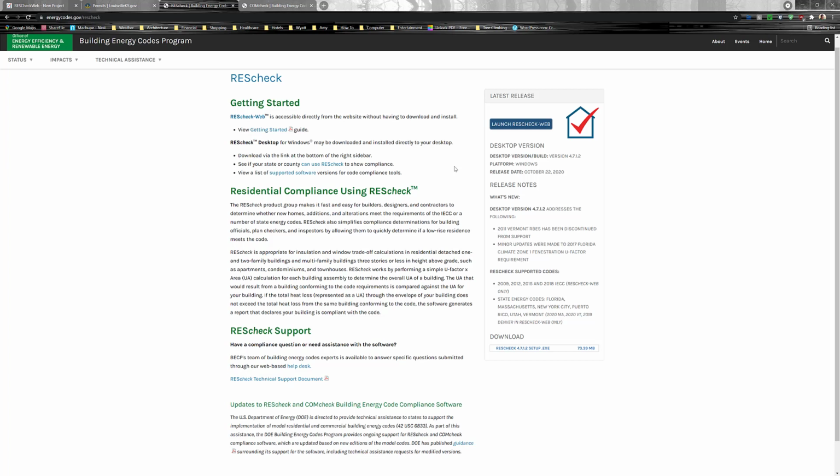And that will involve doing certain things on the mechanical systems and on the electrical systems, like potentially insulating pipes, for example, and sealing penetrations that you agree to do and do a blower door test. And these things overlap what the mechanical engineer is doing or the electrical is doing, and they need to be made aware of it. But you don't have to work directly with them to complete a full Comcheck.